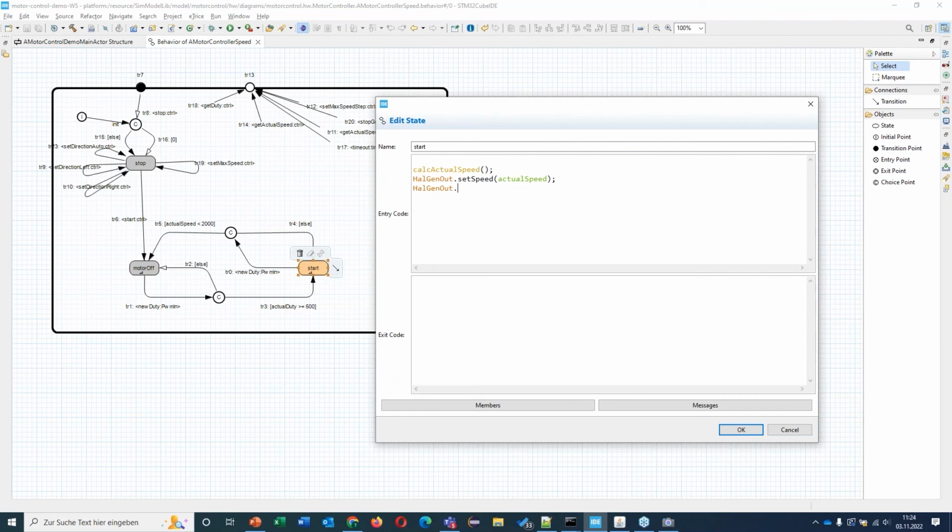So if I want to see what else I could do, I could change the speed, I could change the direction. And for example, by setting a wrong speed now, I could actually do failure injection. So for example, the motor is not fast enough. So what does my application do on that? Does it create the right error condition and does it shut down? Or I could also change the direction just to see whether my application finds out. So those are typical examples for failure injection here.